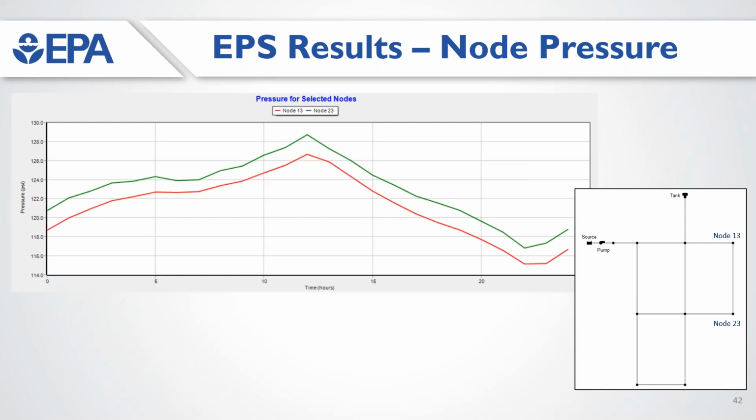For extended period simulation, you can run it. The hydraulic simulation is relatively fast. Lots of people care a lot about node pressure because they want to make sure the PSI is high enough for their system. Again, you can plot the results for 2 nodes, and you can see the pressure goes up. Again, this system has a 24 hour pattern period, so everything repeats every 24 hours. If you set the pattern period to be 1 week, the simulation will repeat every 1 week.